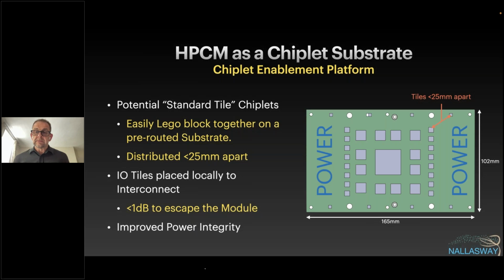And would you imagine that these are super fine pitch die-to-die interfaces, or can they be? Well, it's organic is what I was assuming. So you're 130 micron or thereabouts. Yeah, I wasn't thinking advanced substrate. There are lots of different ways of doing the advanced stuff like the EMIB, etc. But if you had a standard CoWoS, you could potentially have a CoWoS die with all of the advanced chiplets on top, and then mount this onto this as a package substrate instead of putting a CoWoS into a normal package. So you could potentially do that.